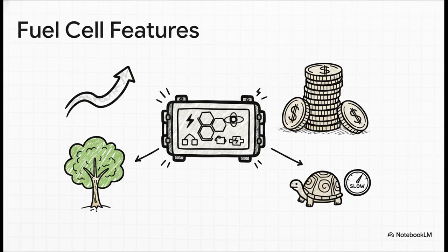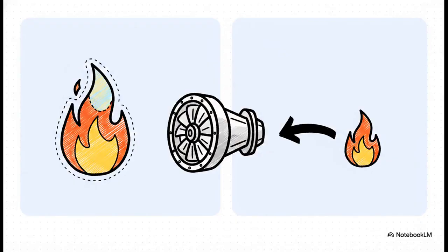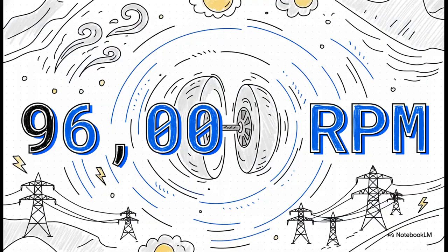It's a real bottleneck. So when we're evaluating the fuel efficiency of local generators, like microturbines, we really have to distinguish between two specific values. You've got your higher heating value, or HHV, and your lower heating value, LHV. The HHV is the gross heat of combustion, meaning it actually includes the latent heat. The LHV, on the other hand, is just the net heat of combustion. Knowing this difference is absolutely vital so our engineers aren't accidentally overestimating the true usable heat output of these small but mighty power plants. And speaking of mighty,